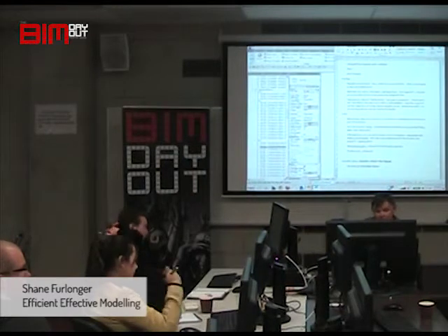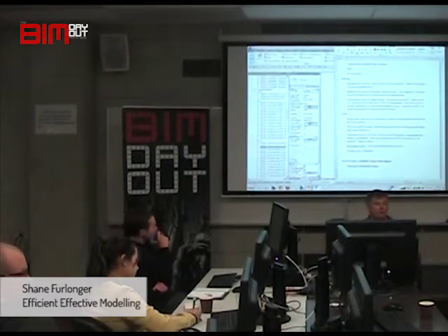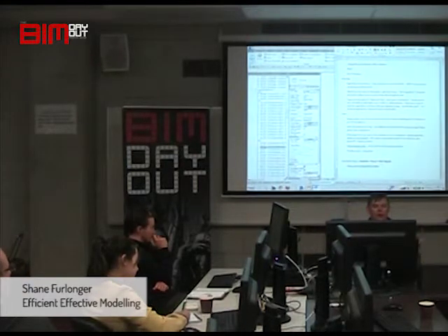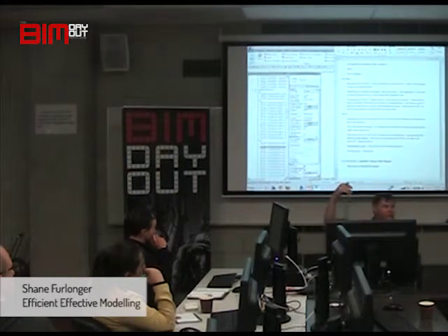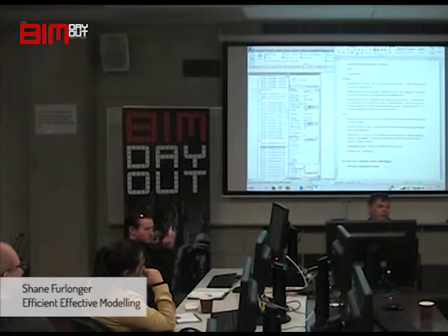Well, this is the next one, which was what I was going to talk about. How do you actually set up your walls? Because a lot of people will go, oh, I like to go level to level and offset, or I like to go unconnected to a certain height. Then you go and change your levels, and the walls behave differently, obviously. I like to use level to level with offsets, mostly.